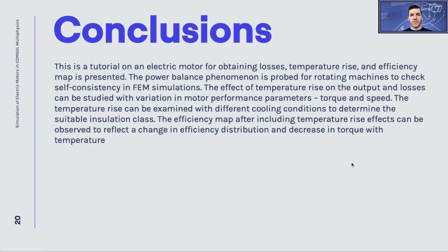Okay, so just to wrap up, with this model, you can easily calculate different scenarios for different motor speeds, with different driving currents, with different material properties. So you can easily create an efficiency map for an electric motor. And since for this design we know the analytical solutions for the efficiency map, for example, we can easily validate our solution, whether it matches that part or not. So we can fine tune our finite element model here.